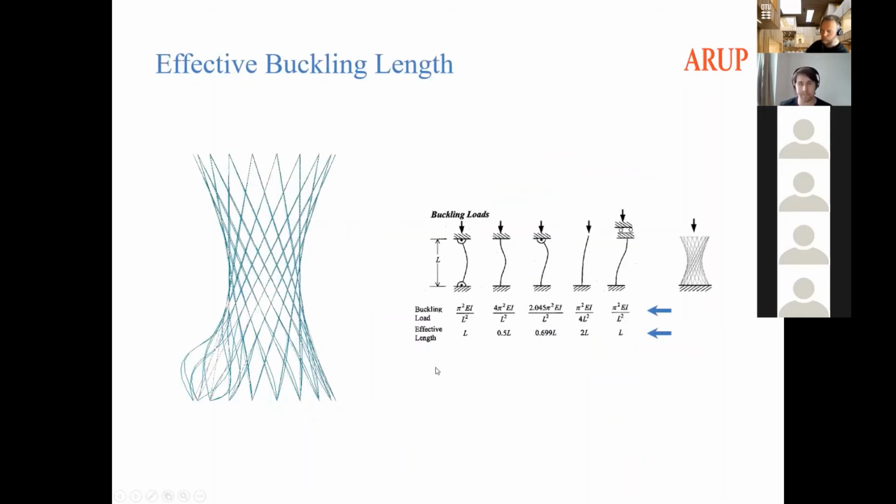Now, by having a structure standing alone without the ramp ring, this of course meant that we had another buckling length. We already had a global buckling assessment of the tower because it didn't really fall into any of the standard Eurocode buckling lengths. So we were already using this to find the elastic critical load factor. And as it turns out, the temporary stage with only the ramp ring in is actually the governing part for the design of the diagrid columns.